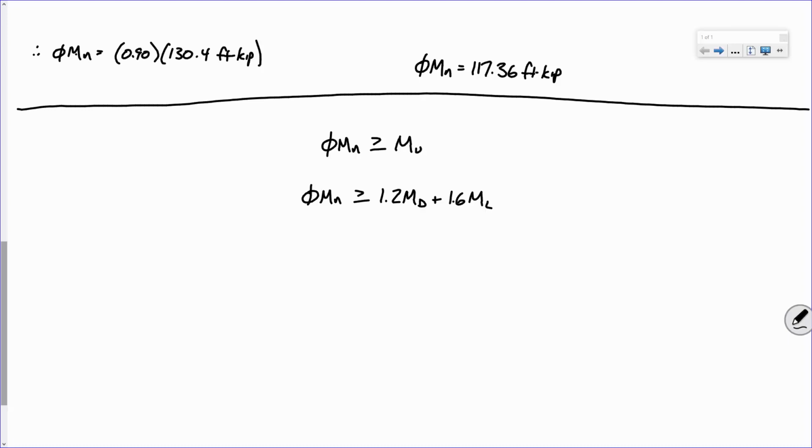Now, one particular point I'll make about this problem, what dead load must all beams be able to withstand? Their own self-weight, okay? Now, in order to determine the self-weight of this beam, theoretically, we would need the beam's width and the beam's height. Do we have the beam's height? No, we don't. We only have its depth. Now, we can make a guess and say its real height's about 18 inches, because it's usually 3 more than the depth. But I'm actually just going to conservatively neglect it. When you look at the numbers you'll see in a little bit, it probably wouldn't matter anyway. But you can make a guess if you need to. For the purposes of this, we're just going to neglect it.